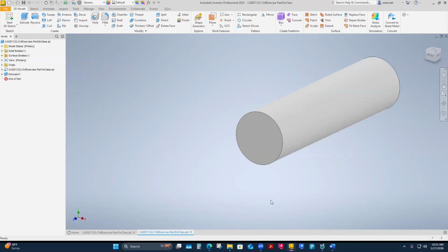You have to reference a pipe schedule chart, a pipe size chart. I don't think I've loaded that in. I maybe have loaded in the description that I've got to go look for a pipe size chart to even know what dimensions to work with. The engineer's sketch does have the pipe size called out, but the weird thing about pipe is a 2 inch pipe doesn't measure 2 inches anywhere on it.